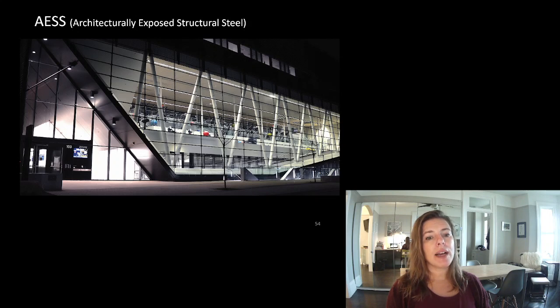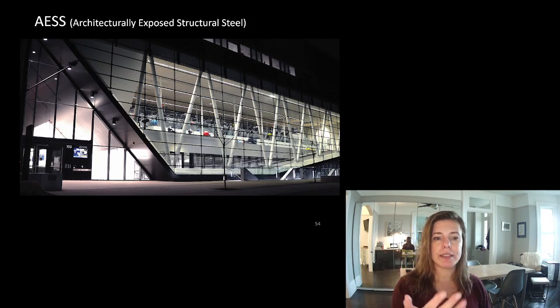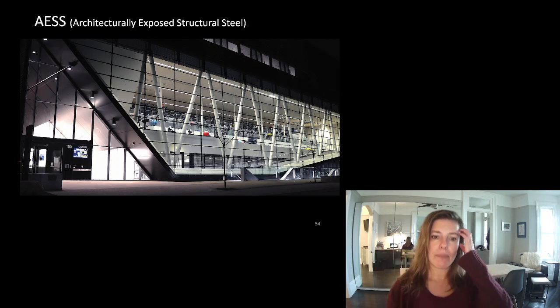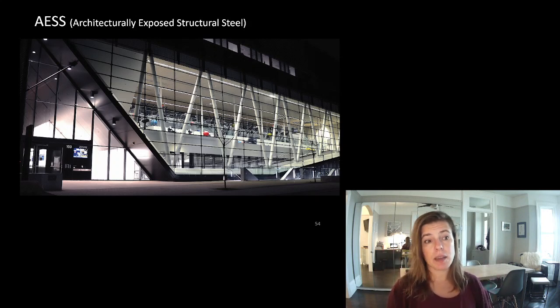One of the things about intumescent paint is it's very expensive, so we try to do whatever we can to limit it. Plus, it's got a bit of an orange peel texture, so it's a little bit dimply and bumpy. Some architects hate it, some don't mind it. So knowing that you've got steel exposed, and if you can have it exposed, and if not, what you need to do to it. And then for both of those, how to specify how to make it look pretty can be important.